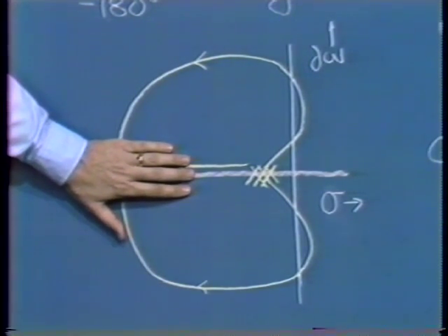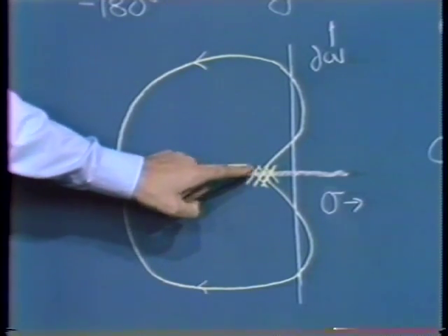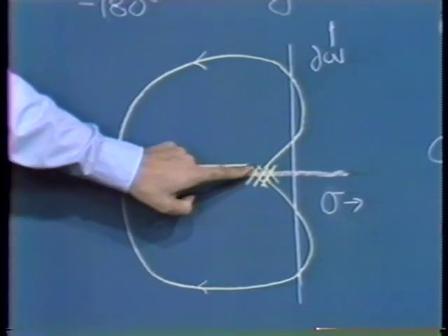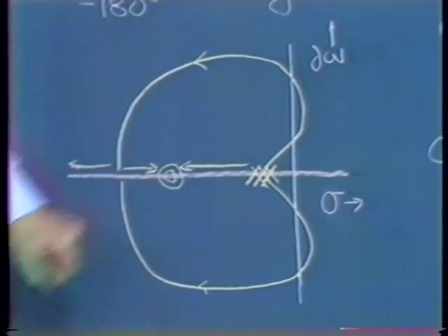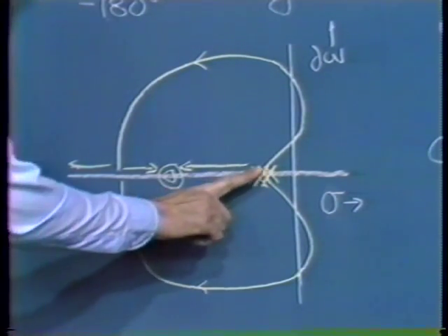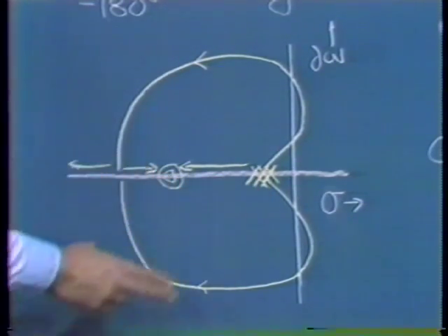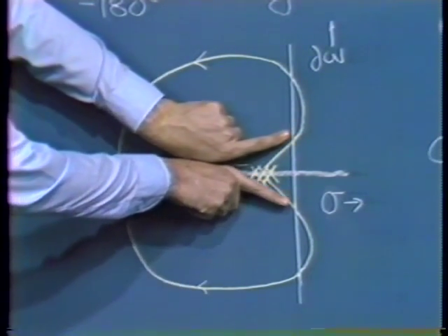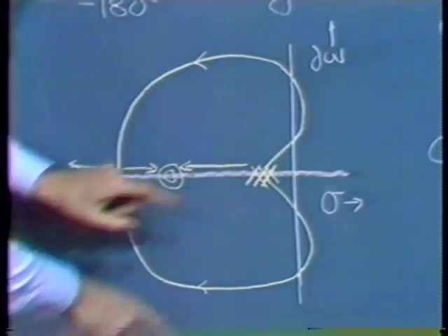Initially, we should be able to ignore the 2 zeros, their high frequency singularities, the ones that are further away from the origin. And so we'd anticipate that this triplet of poles would give us the usual plus 60 degrees, minus 60 degrees, 180 degree branches in the s-plane. And again, depending on the relative spacing of the poles and the zeros, it's very possible that for some range of the A0 F0 product, there are 2 branches in the right half plane.